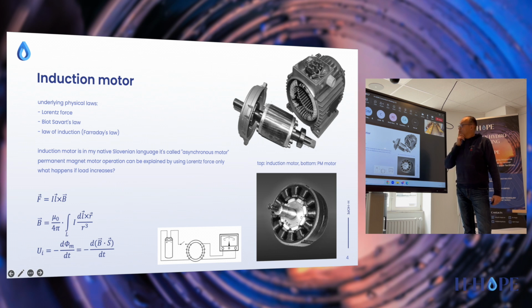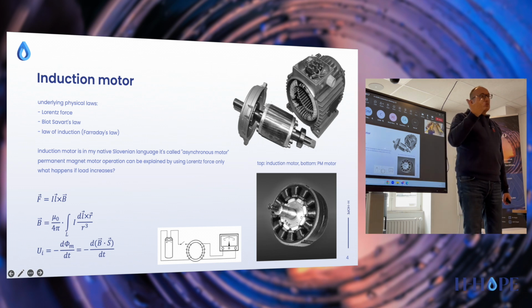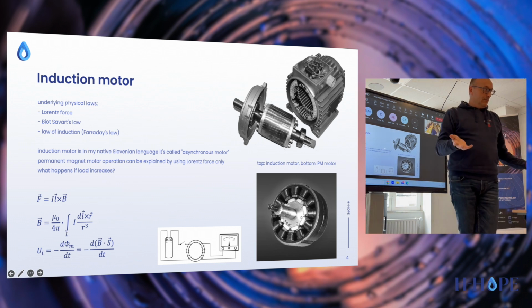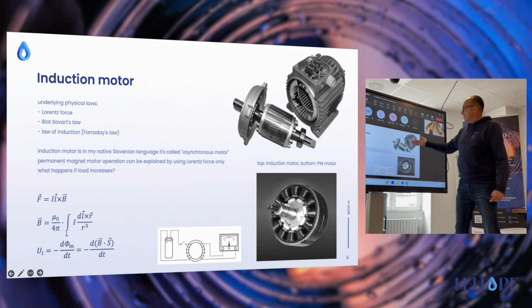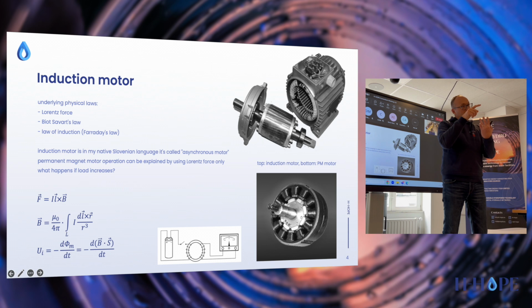And then we have inside the magnetic field the rotor. Now it's out, but you may imagine that you can put it in. Let's assume that in the beginning it's stationary, right? So the rotor itself sees a large change of magnetic field, because it is stationary and the magnetic field is rotating around and overtaking the rotor.